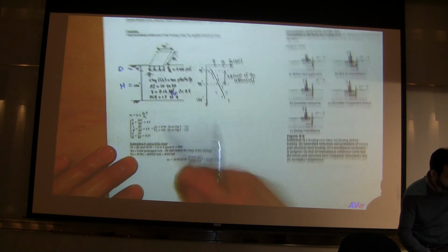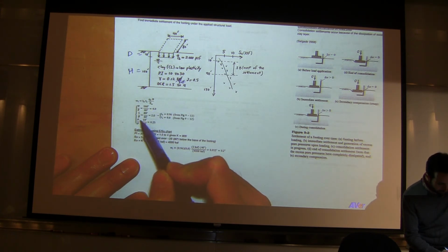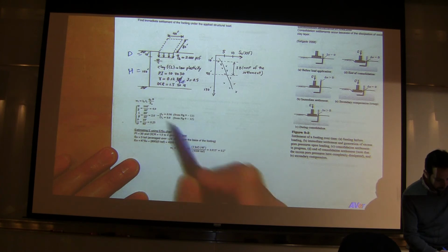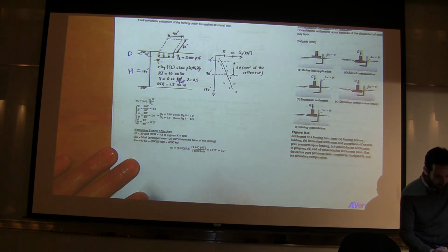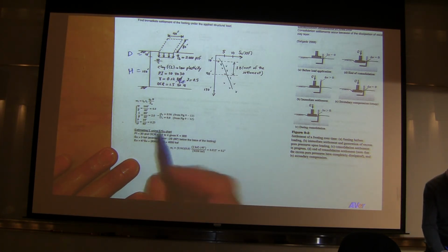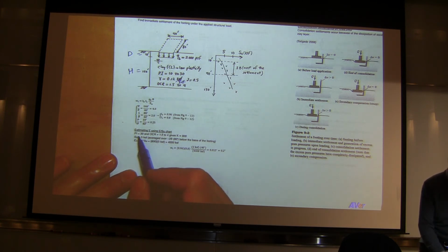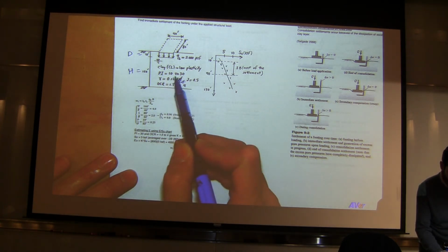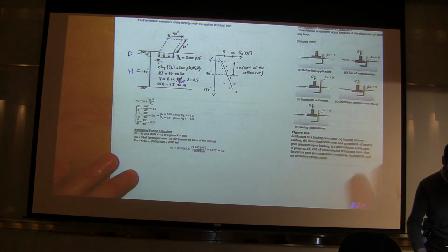So then you can plug in the values. That's the equation. H over B is this, L over B is that. You go through those 2 equations, you get the I0 and I1 value, and then you have to estimate elastic modulus using E over SU chart. So PI is less than 30, that's given, it's between 10 to 30, and OCR is between 1.5 to 4.